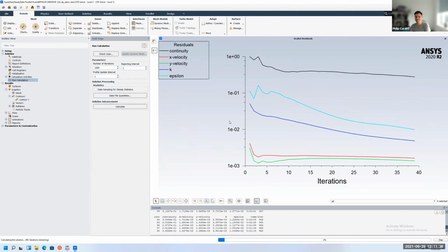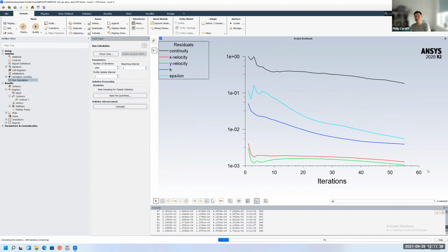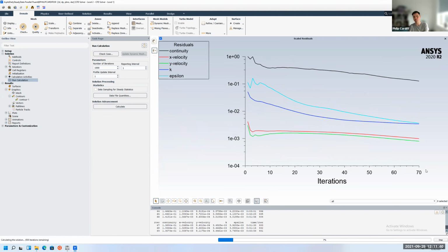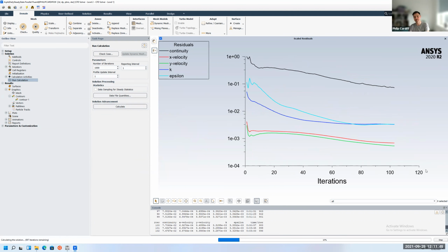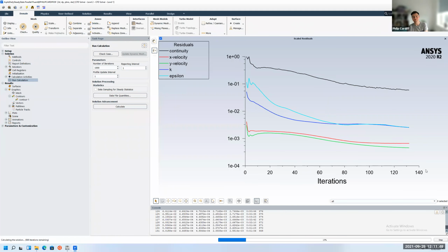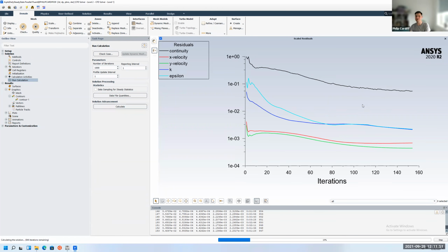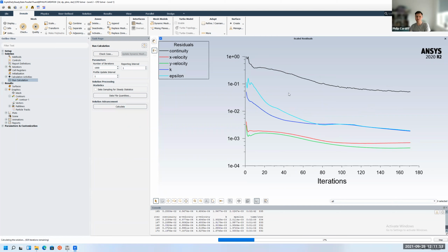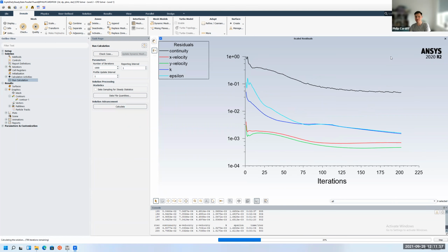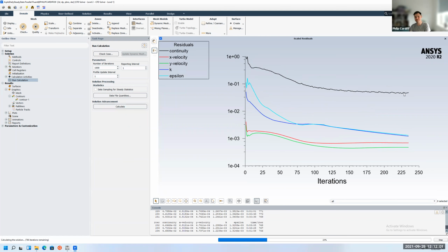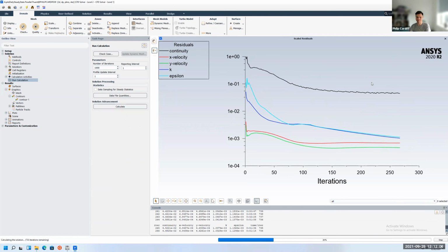There's a couple of things you'll notice. They're a little bit subtle. One is each iteration is a little bit faster in simple than a coupled solver. But that might not be so important here. The more important thing is the residuals tend to converge slower using the simple solver. If you remember, we have to get everything down to 1e-3. But as of now, if you look at our continuity equation, the residuals are not converging so well at the moment. The other ones are going down.